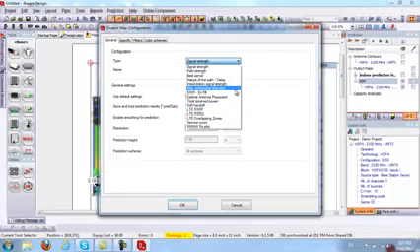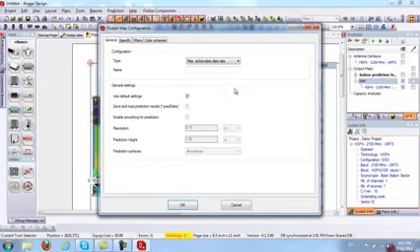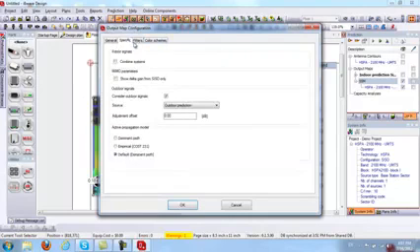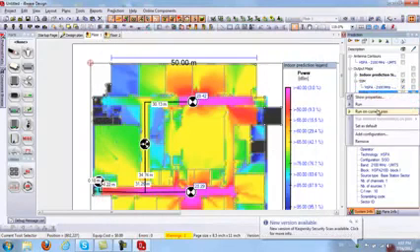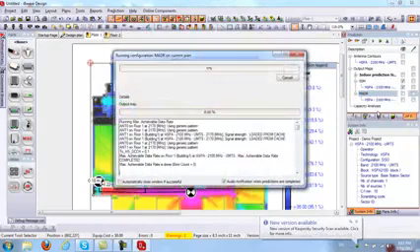So we'll go ahead and select max achievable data rate to view the data rate inside my floor plan. So I'm going to name it max achievable data rate. And if I go to the specific tab, here you have the option to consider outdoor signals or not. So I will not consider outdoors in my case, and I will click OK. Once you do that, I can just right click on my map and run it on my current plan.